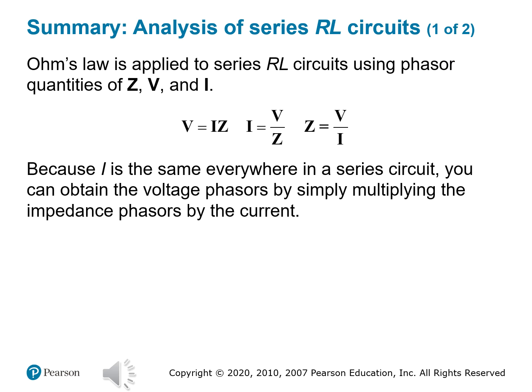Here's the key advantage of working in phasors, though. In a series circuit, current is the same through all components. So that means you can calculate each voltage drop by multiplying I, the current, by each impedance value, R or jX sub L.